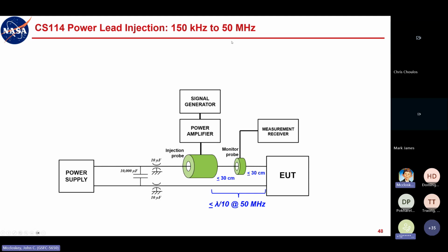And 400 megahertz is totally overkill for controlling conducted susceptibility on power leads. We only control conducted emissions up to 50 megahertz. So there's no particular reason to do CS above 50 megahertz, because at high frequencies your input filters pretty much squelch anything. So we've generally found over the years 50 megahertz is a more than sufficient upper frequency for testing conducted emissions and susceptibility. So one thing that works in our favor here is limiting the upper frequency to 50 megahertz.